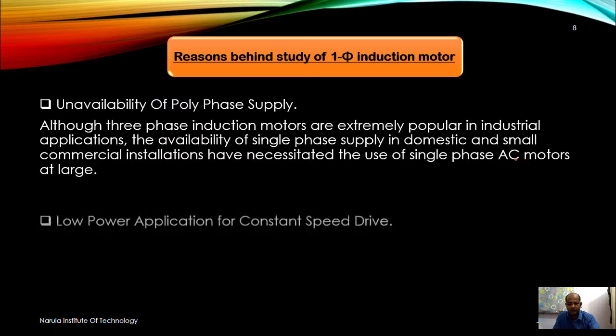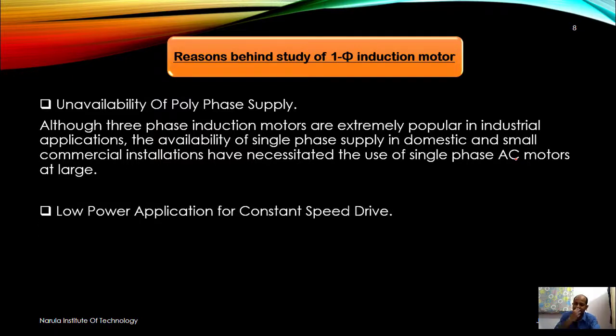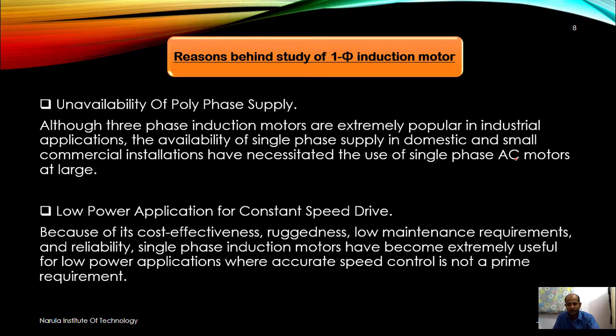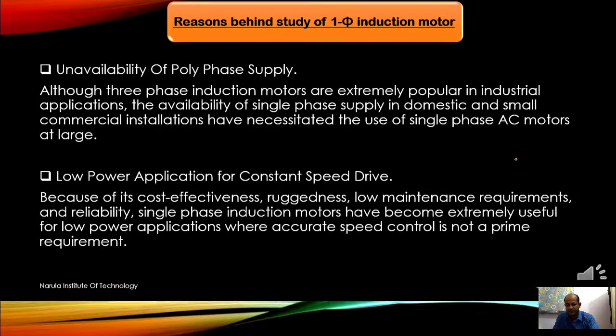Okay, so the second reason is low power application for constant speed drive, and I have explained that where accurate speed control is not required in low power application, there single phase induction motor is preferable in comparison with three phase induction motor due to the cost factor, right?